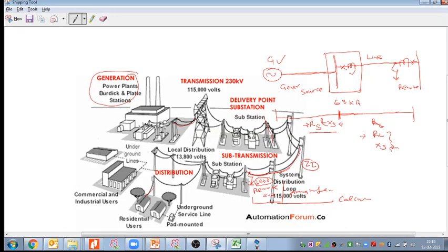Till here we know the 63 kiloampere, right? I don't know what the fault current is here, 80 kiloampere, 90 kiloampere. I'm not aware of that, because that value is not given in the tender. The value is given for my substation voltage and that fault current. So for my 400 kilovolt, as per the CEA,